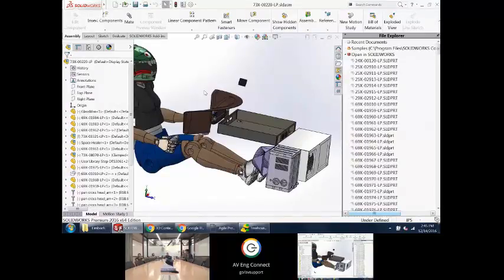I don't think so. I think when you selected multiple components and right click, form new subassembly. Yes. You showed us the option of whether it's going to be internal or external. Okay. Yeah, that's right. The thing is if you choose not to do it externally, it'll save as what's called a virtual part, but that has no external file.